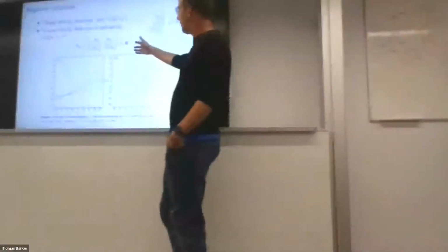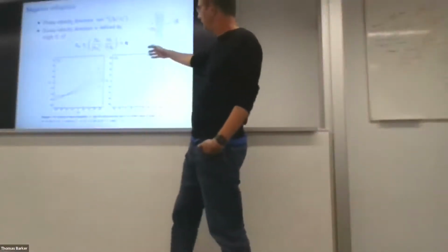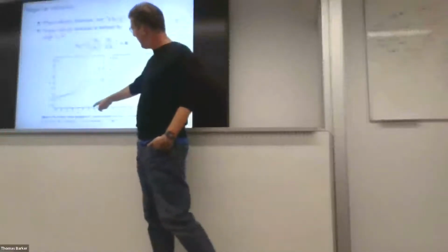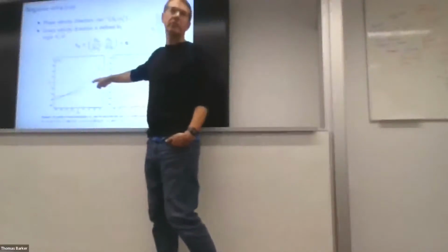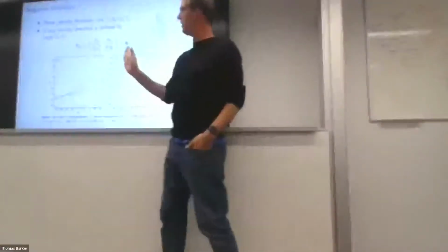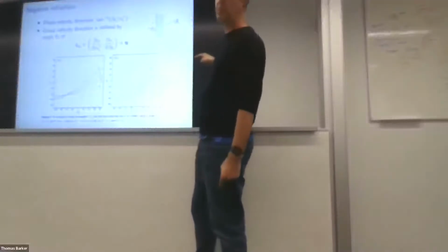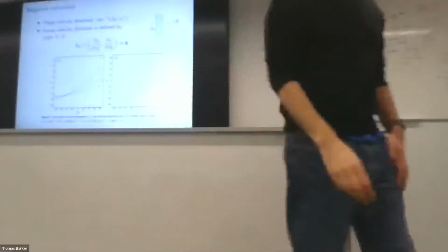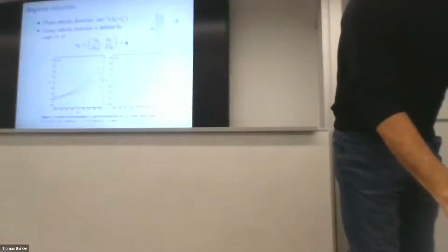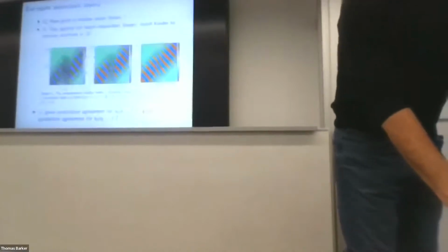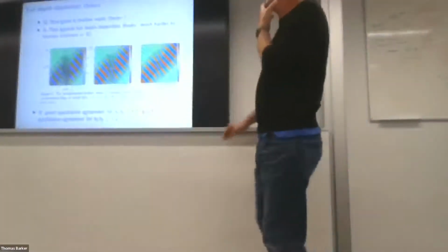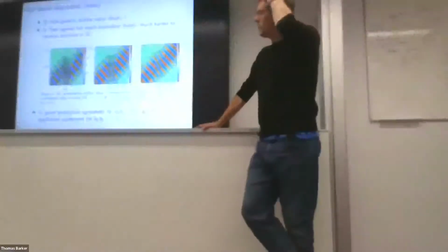Okay, and you can actually work out when this happens by looking at the group velocity, which propagates the energy. So, for example, in this case here, you can have positive angles of incidence, negative angles of transmission. And that would be a wave coming in this way and then bending back that way. Okay, so it's very neat when you're using shallow water theory because everything is explicit and you can see exactly how things are going to work. So these are the types of pictures that you can get.